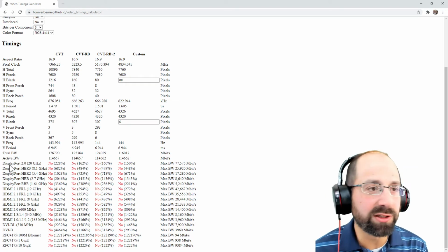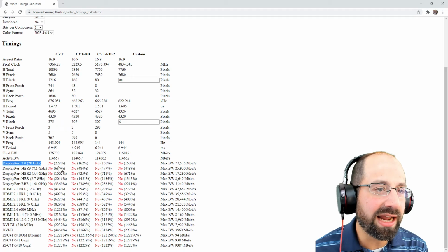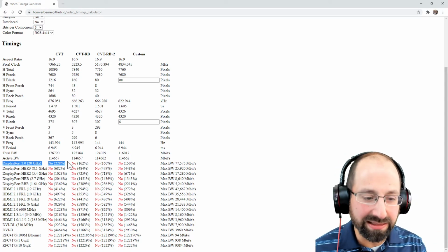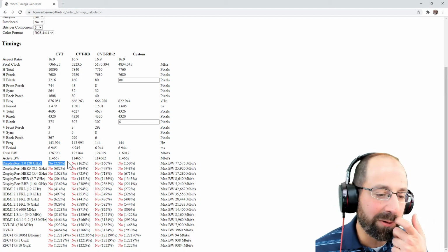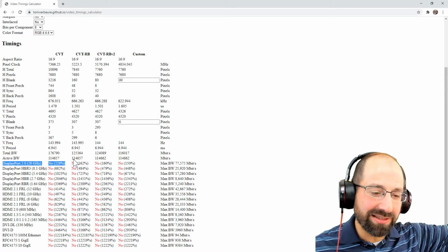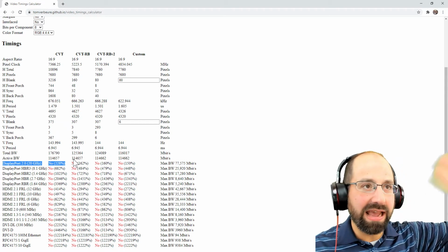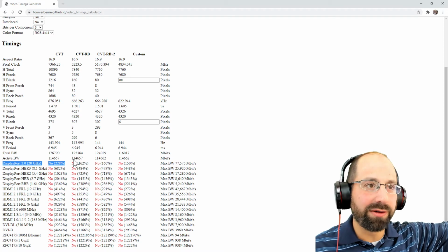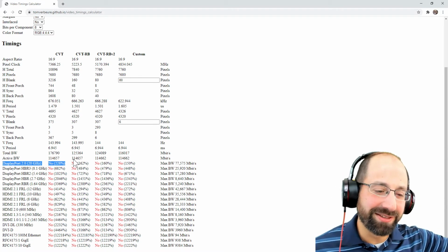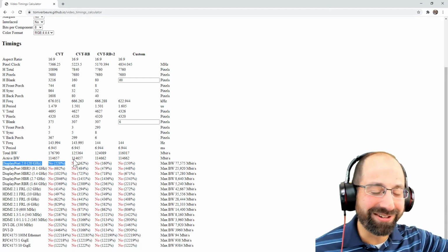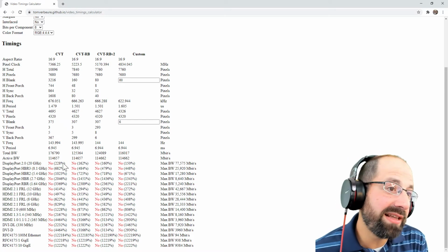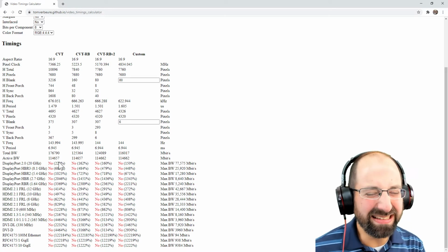Right, using multiple display ports, according to this calculation, it has to use 3 though. So I do wonder about that, or if there's ways it can do it by compressing that stream to get that information to fit over the cable. So it's not true 8K, I guess, right? If you truly wanted to show 8,000 by 4,000 different pixels with no compression whatsoever, you wouldn't be able to do that with a single DisplayPort cable. But to me, just looking at those throughput requirements, it's a little mind-boggling.